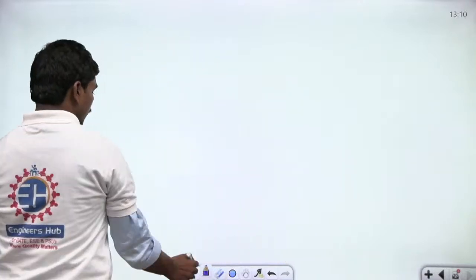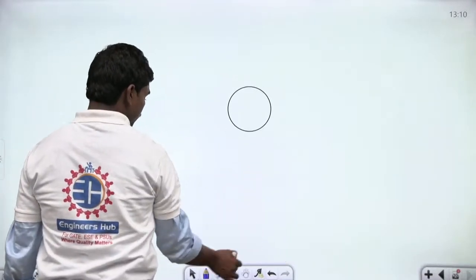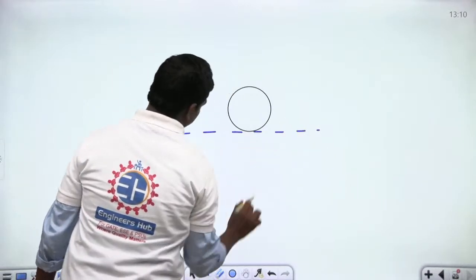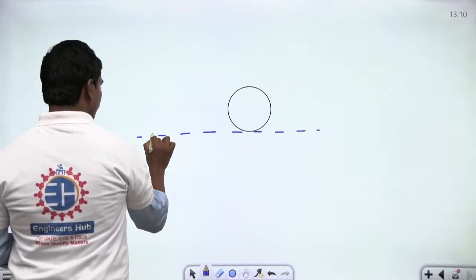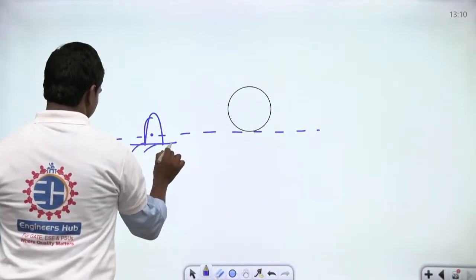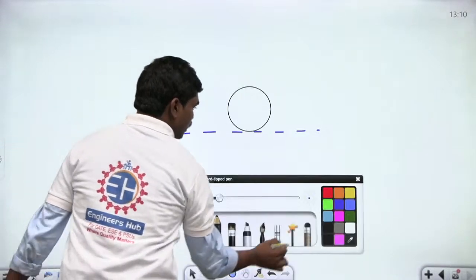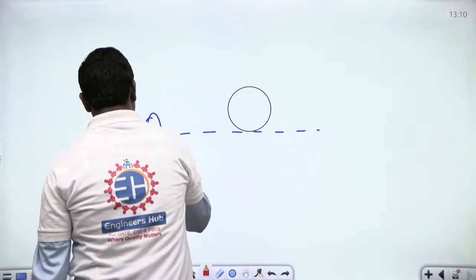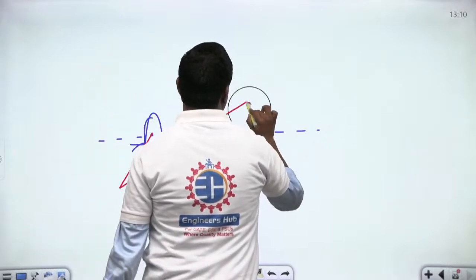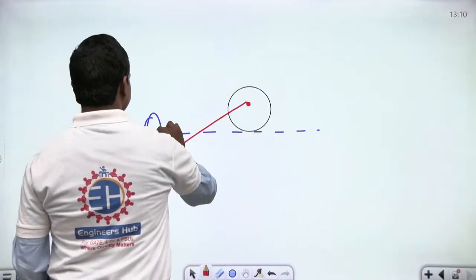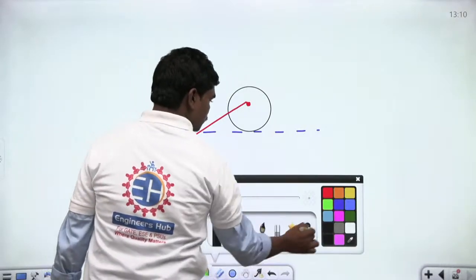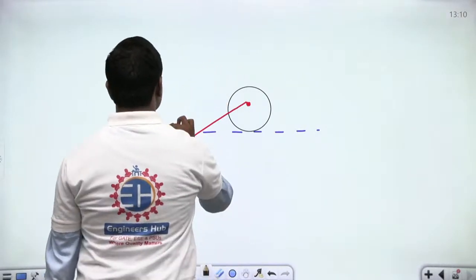And of course some instantaneous centers question is also there. For the instantaneous centers question, I would like to show you something. We would like to plot all the instantaneous centers of a given mechanism. So you could clearly see there is some hinge here, and there is some crank and other elements here. And the instantaneous centers, of course, are the lines joining all these things. So let us try to do that.